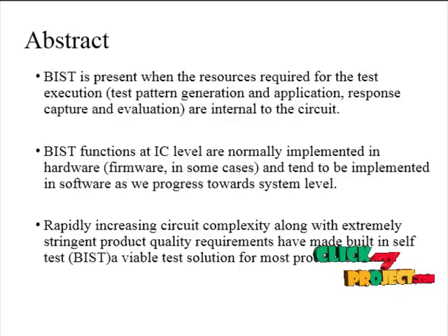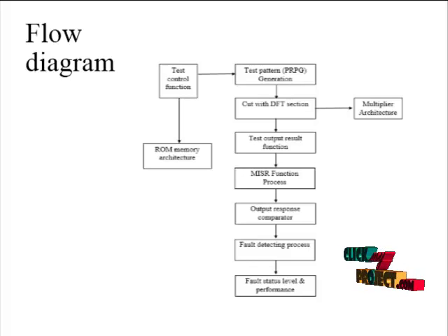One conceivable but expensive solution is to probe the prepackaged dynamic random access memory. The easiest and most cost-effective solution is to add built-in self-test circuitry inside the chip. The BIST engine provides an efficient mechanism to deterministically drive and receive patterns on the memory bus, along with automated data checking capability. These features can be used to swiftly identify and isolate bugs in the silicon validation phase. Furthermore, given the continuous increase in system reliability requirements and the current trend of adding more complex features to achieve higher reliability goals. Next we are going to see the flow diagram for our product.